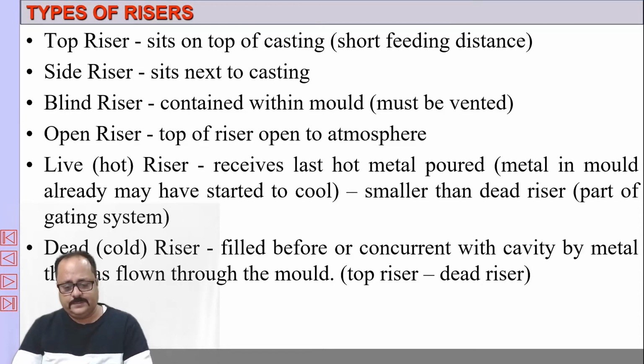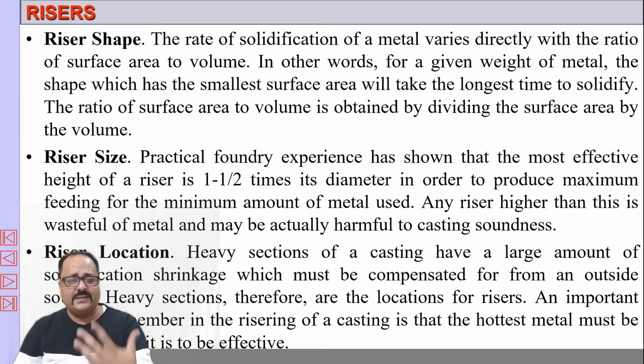Now, one important aspect: riser shape. A riser shape can be cylindrical, rectangular, or a square cross section, it doesn't matter. What matters is the ratio of the volume of the riser to the surface area.